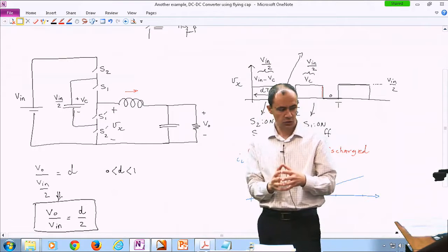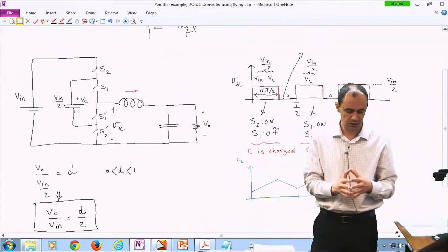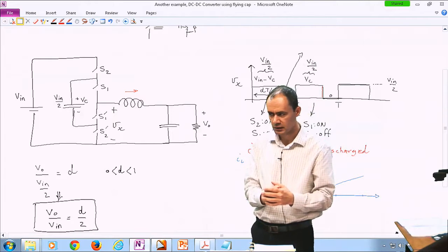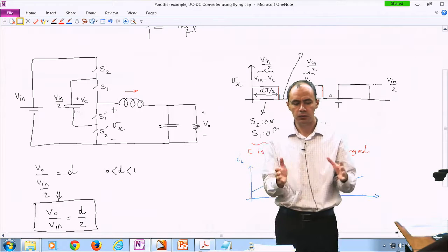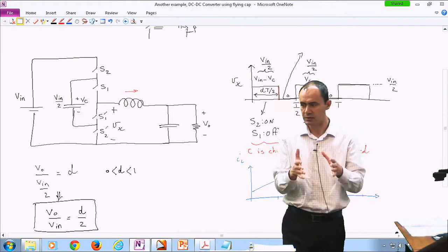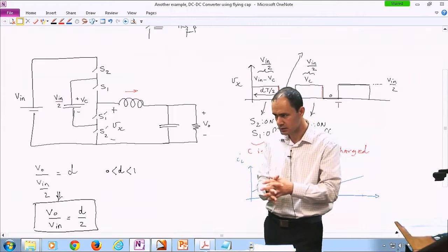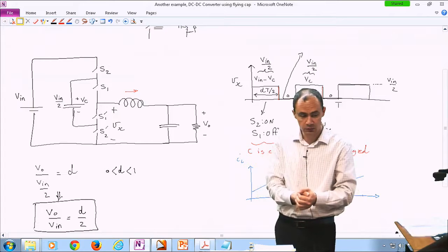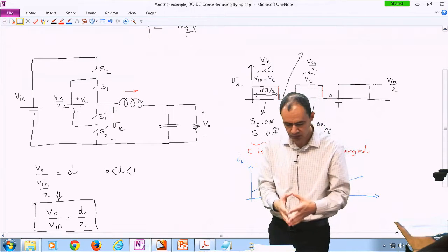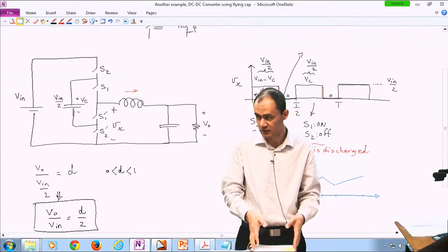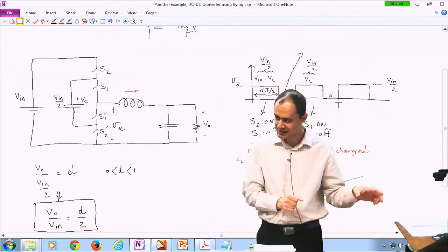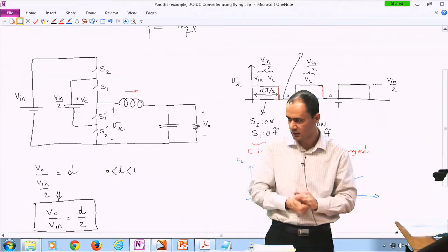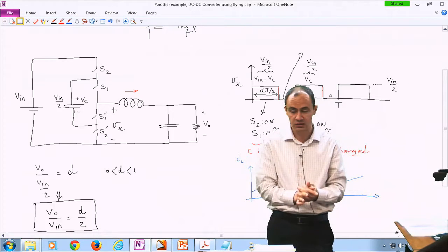This doesn't do that. So the question is, if you have a low voltage, high current application, and we want to put a bunch of elements in parallel, so each one of them is seeing part of the current, not the entire current, can we use such a device like this? This topology by itself cannot do that. However, with the whole concept of putting converters in parallel, or the multi-phase converter concept, you can use this as one of the cells of a multi-phase converter. You can use 2 or 3 of them in parallel. In that case, you can actually afford that. But this converter by itself cannot do that, unfortunately.